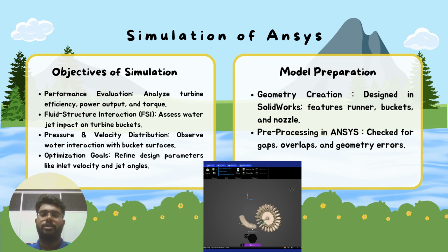To achieve these goals, we started by designing a precise 3D model of the turbine in SolidWorks. This included key components like the runner, buckets, and nozzle. Once completed, the model was exported as a STEP file to preserve dimensional accuracy and then imported into the ANSYS Workbench. In the pre-processing phase, we checked for gaps, overlaps, and unnecessary details in the geometry to reduce computational load while maintaining accuracy. Critical areas such as the inlet, outlet, and walls were labeled using name selections, making it easier to apply boundary conditions during the simulation.